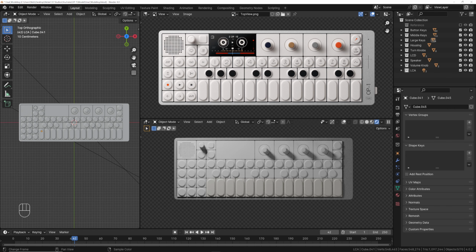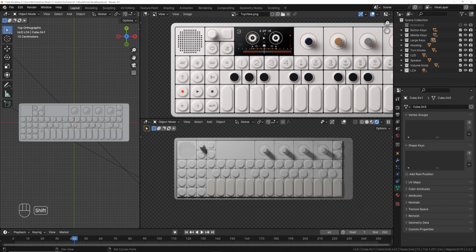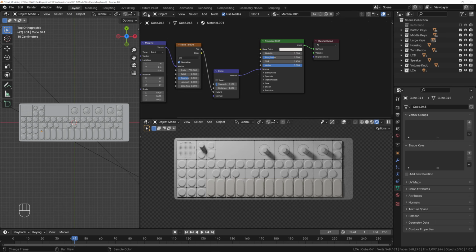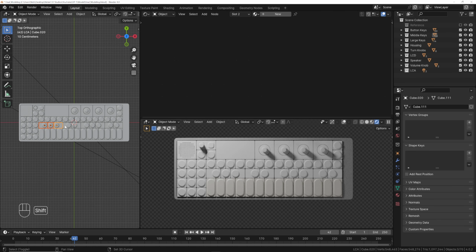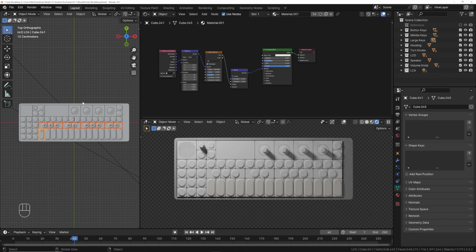We'll go back and adjust this at the very end when we're using the reference image, but these tabs right here have the exact same plastic, and then they just have this black material here. So what we're going to do is set up these tabs to do that same thing. So we're going to go back into the shader editor. On these pieces, we're going to select them all, and then click this one last, and we're going to do the same thing, Control L, link materials. So now these all have the same base plastic color.